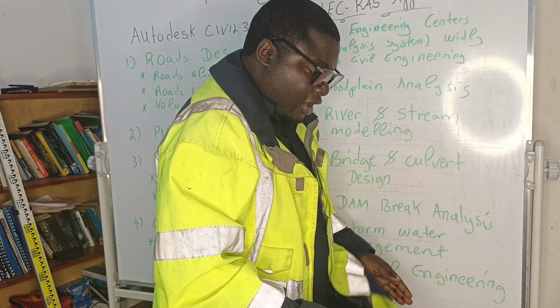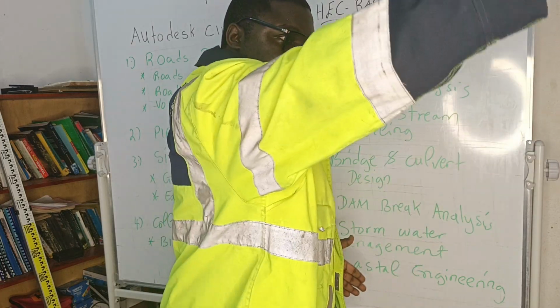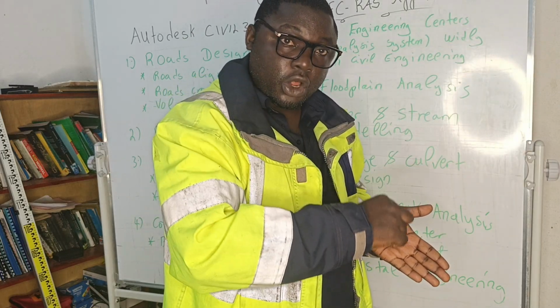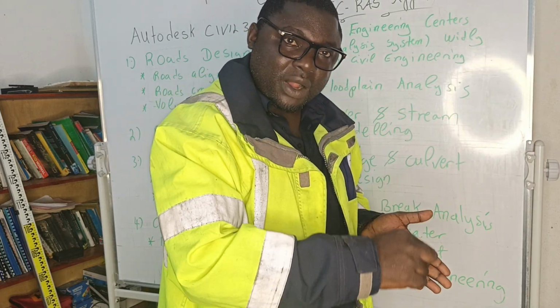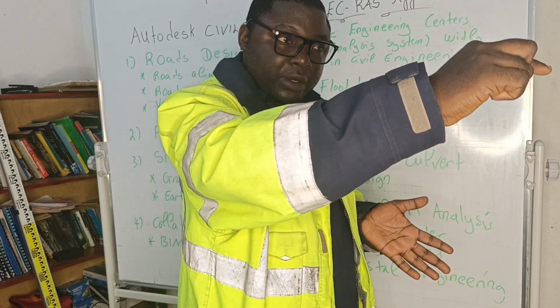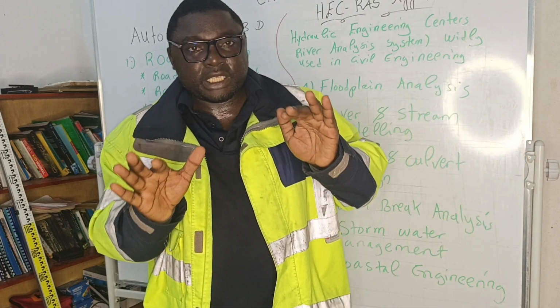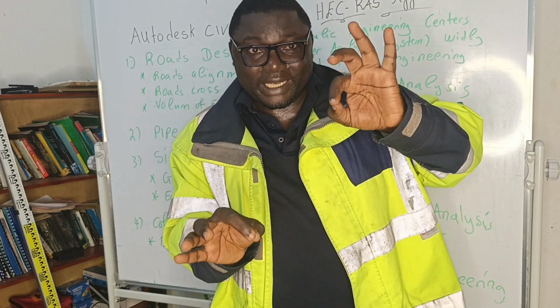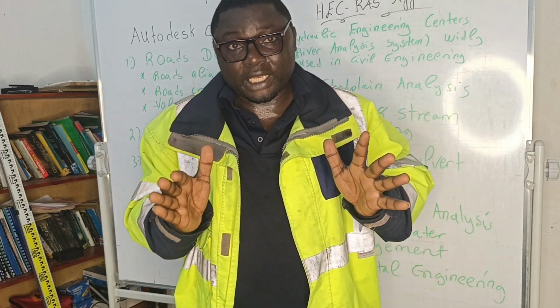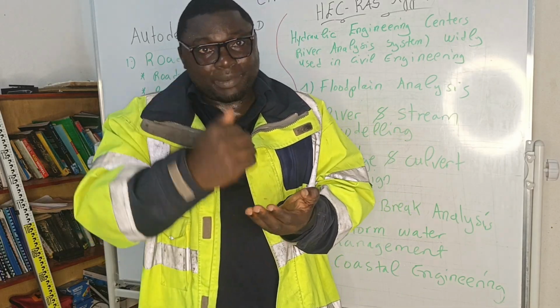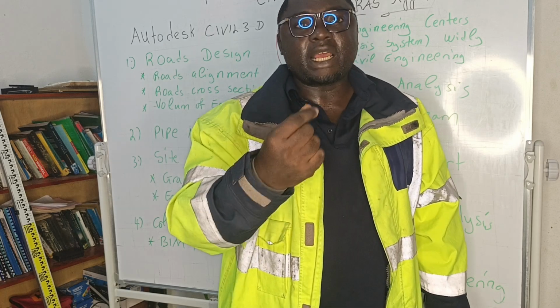Within the central axis of that road from Akure to Ife, that is the longitudinal section. We're going to study how to come up with a longitudinal section. We use the longitudinal section to study the gradient of an area that has been allocated for a road project. We study the gradient and we can now adapt it to a suitable gradient that cars can take.